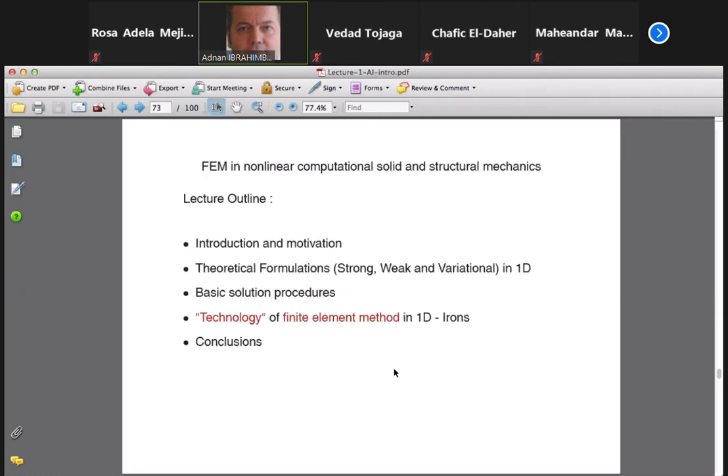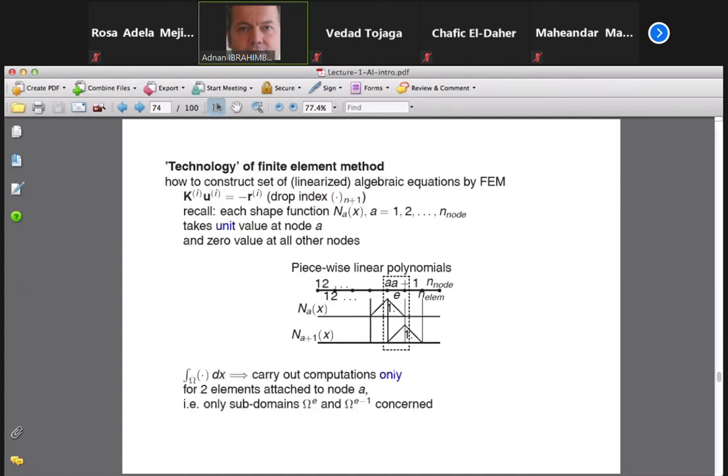Now, the second part of this technology, the finite element method, would be going into so-called isoparametric element interpolations. And that's what I wanted to explain. So imagine now that, to construct the solution method, you use a number of these truss bar elements. And for some reason, you decide that not all of them are the same, because you want to adjust your approximation in a better way to a particular loading, which might have a steep gradient somewhere and maybe not much going on somewhere else.